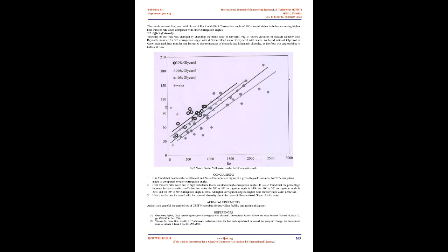The flow pattern adopted here is countercurrent flow. The experimental setup consisted of corrugated PHE storage tanks for test fluid and hot fluid, rotameters, digital temperature indicator, pumps and manometer. The experiments were carried out in the plate heat exchanger having 5 mm spacing. The experiments were carried out with the biodiesel of viscosity 0.8 cP at 35°C as test fluid.